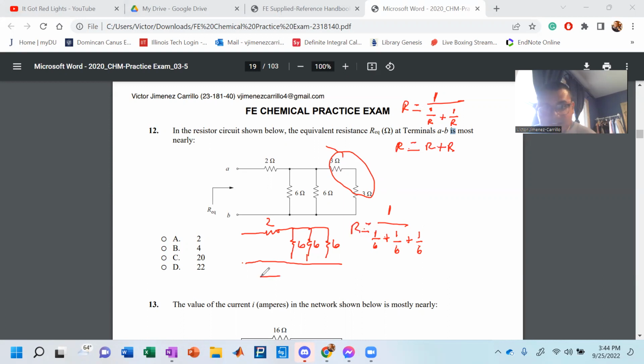And then this rewrites again. This is 2. And all of this turns into, guess what? 2. So there's 2 and 2. And then these are, again, in series. And then the parallels just stay in parallel. Unlike these that turn into one straight line, they just stay in parallel. So 2 plus 2 is 4. And that's B. Light work.